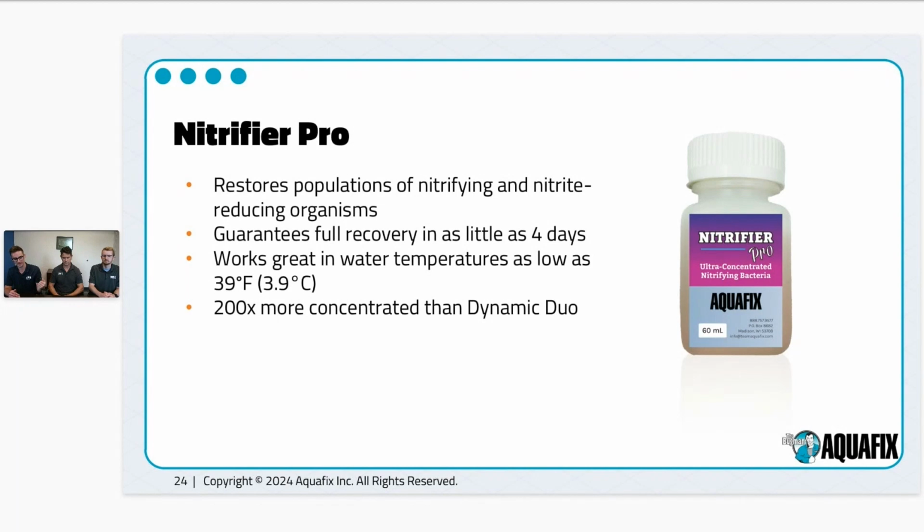Once everything is kind of set in stone, once you have BOD removal, once you're settling properly, and really all that's lacking is simply ammonia removal, that's where you can then add nitrifiers. Once again, make sure that whatever stressor caused this issue is no longer present. Then it's totally safe to add nitrifiers. It's really just a blend of concentrated nitrifiers suspended in liquid. Simply add that to your aeration basins, and within 4 days, we expect full recovery.